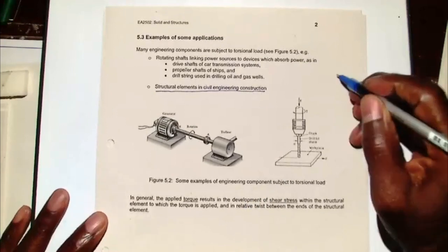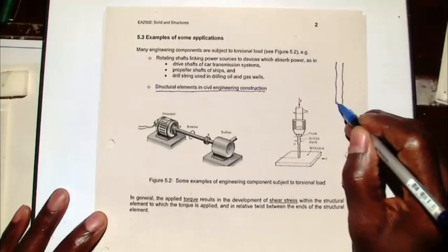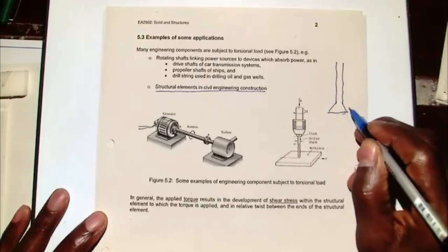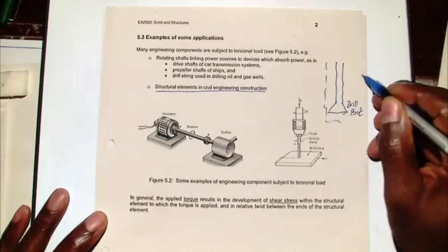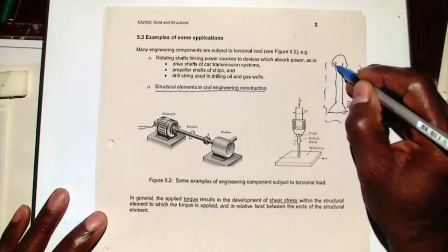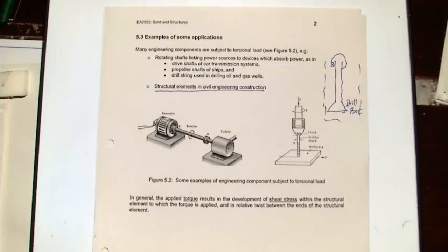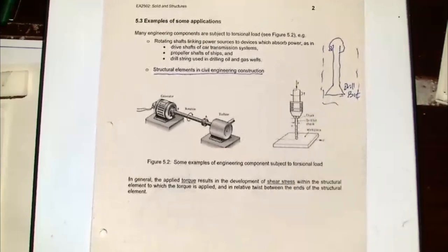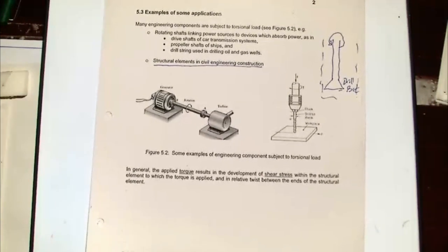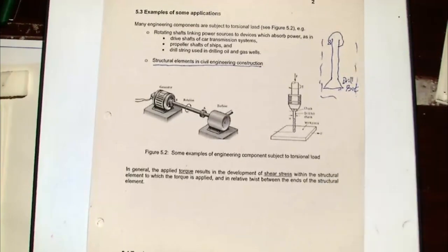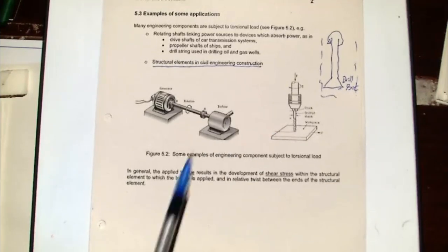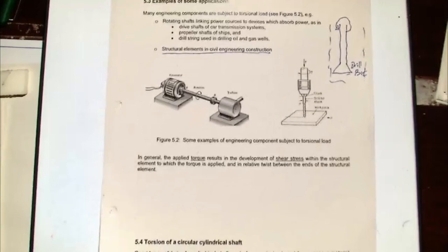If you have what is called a drill string with a drill bit at the bottom, that is your drill bit, and you are drilling a well. In order to do that, you have to rotate this. You have to continue to rotate it so that the drill bit will continue to drill. Therefore, it's exactly the same as that. So there will be a torque that you are applying to that particular drill string. What we'll be showing now is the link between the magnitude of the torque, whether in the drill bit or in that simple bar there, and also in that particular case, and the magnitude of the shear stress that you develop.